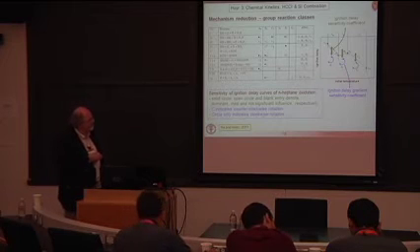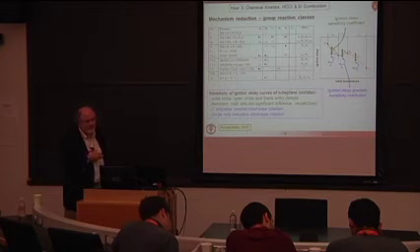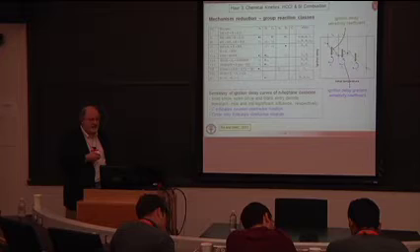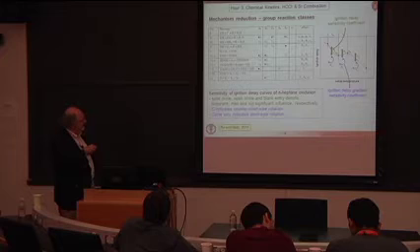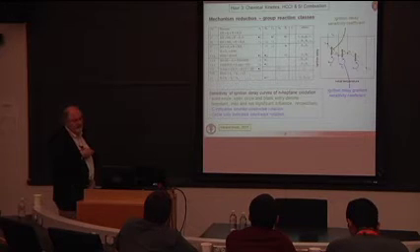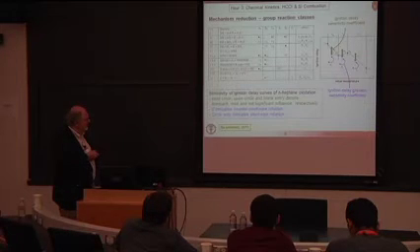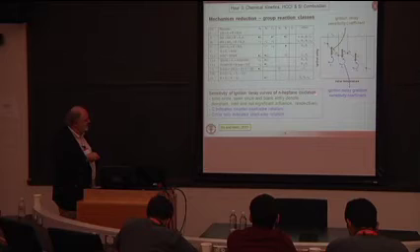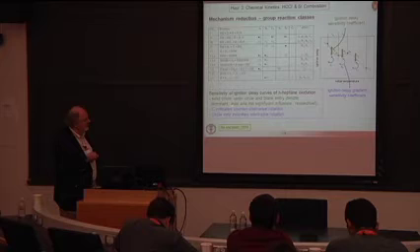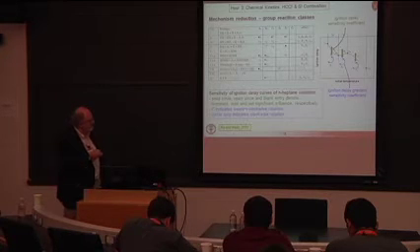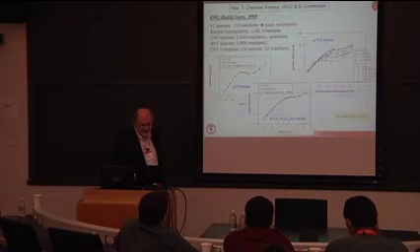Again, the point of this exercise is that if I'm given an ignition delay curve like this from experiments for some fuel for which chemistry may not necessarily be very well understood, but I can kind of represent that fuel through this classic set of classes of reaction, I can match that data using this strategy. So the sensitivity ignition delay curves for heptane are shown over here. Solid circle, open circle, and blank means dominant, mild, or not significant influence, and then the counterclockwise or clockwise rotation effects of each of the reaction steps.